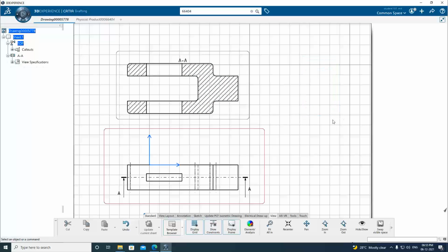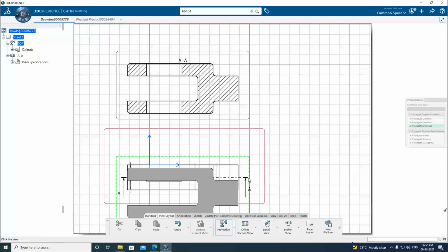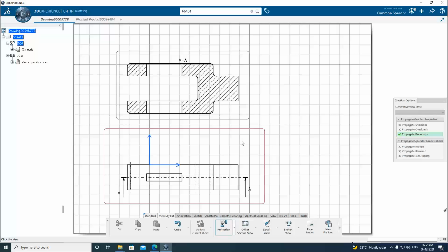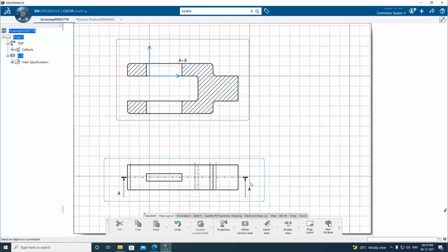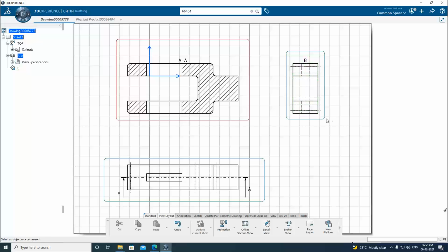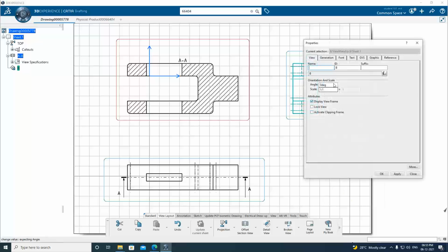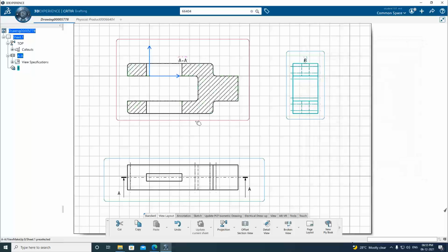So this I will delete and I will recreate the side view. What I have to do is make this the active view. Then I will go for projection view. So the projection view will come here. Hidden lines and other things are on. Now in a sectional view you won't have any hidden lines shown, that you have to remember. So only pertaining to the section it is showing the details.